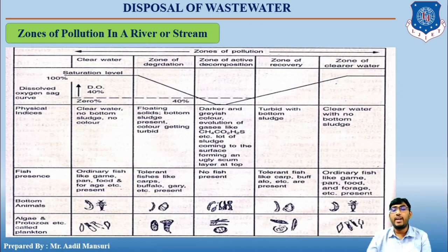Now in this region, the bacteria or flora will flourish. At the upper end, anaerobic bacteria will replace the aerobic bacteria, while at the lower end, the position will be reversed. Protozoa and fungi first disappear, then reappear. Fish life will be absent. Algae, tubifex will also be absent. Maggots and psychoda, that is sewage fly larvae, will however be present in all but most septic sewage.